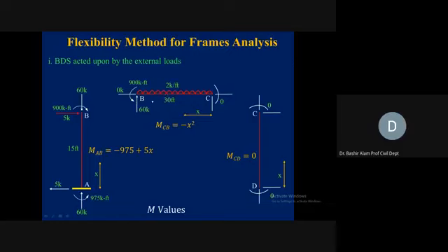Now let's do analysis of this member BC, the horizontal member, which is carrying a load of 2 kip per foot. In analyzing, we need to consider the support conditions. One option is that half of this load should be coming to joint C and half to joint B. But we cannot carry this half of load to joint C. What is the problem?